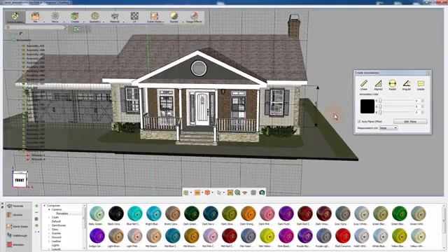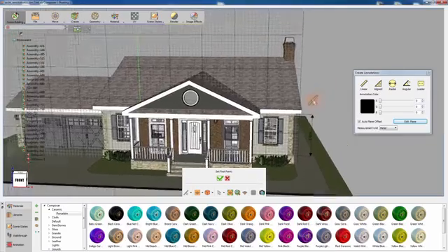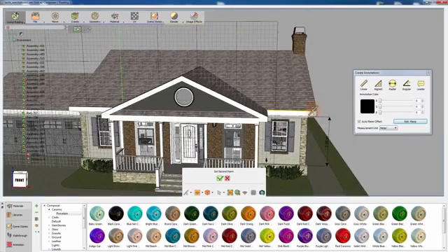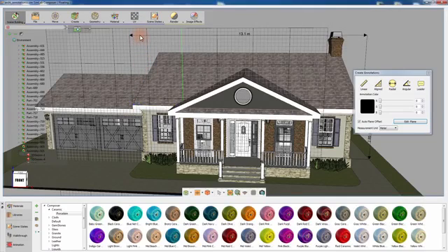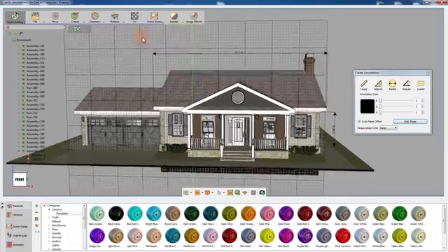To measure the width of the rooftop, create a linear dimension annotation and set the first point at the far right edge of the rooftop and second point to the far left. Move the cursor towards the top and click to set the position of the annotation.